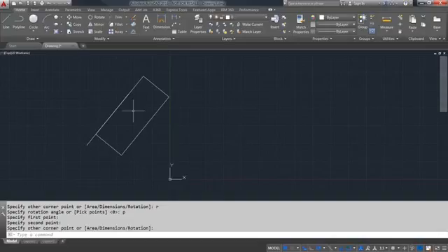The thing is, the page setups are on a per layout basis, though. So, for example, the model tab has one page setup, and all the other layout tabs have their own individually configured page setups. But if you've got a page setup specified in your template, you can choose that page setup then for any subsequent layout you might create within that drawing. And page setups are also transferable from drawing to drawing in several ways. So absolutely, yes, you can set up your page setups to use a specific printer, specific paper size, specific plot style tables. All of that stuff can be pre-configured, yes. So you don't have to do it every time.